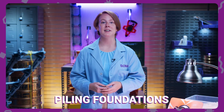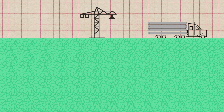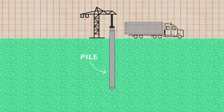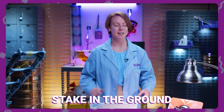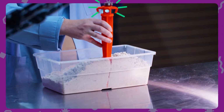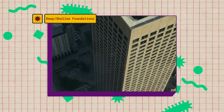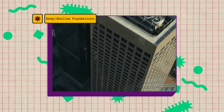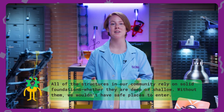The other deep foundation is piling foundations, which are made of pre-constructed piles. Rather than pouring the concrete on site, these piles, usually made of steel, are driven to the construction site and forced into the ground. Piling foundations are as simple as driving a stake into the ground with a hammer. You can see that the deeper that we go, the stronger that the stake becomes. Both deep and shallow foundations serve a great purpose in the civil engineering world, creating a platform to build purposeful structures, from the homes that we live in to the towering skyscrapers that define a city's skyline.